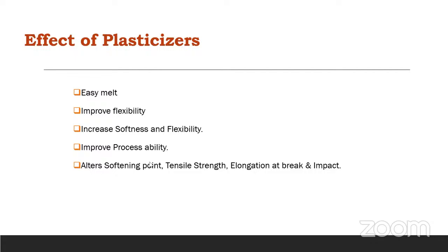The processability, or ease of processing, also increases, and as a result the softening point reduces. Tensile strength reduces, elongation at break increases, and impact resistance in most cases increases, though in a few cases it decreases.